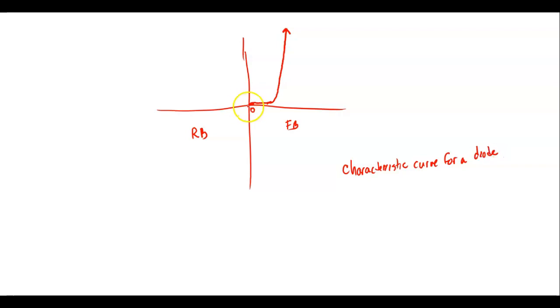Now on this side, when we reverse bias it, you should see a little bit of leakage current. And then when it hits around the breakover voltage of lower, it's going to break over like this. And it's going to slant too. Now what causes the slant? This is the actual R of the diode itself.